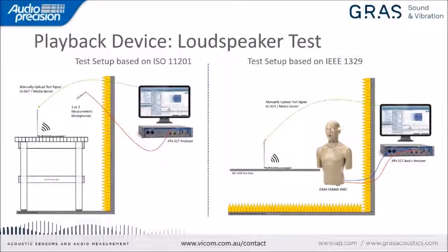Then the test table is placed inside a hemi-anechoic chamber where we typically have one free field measurement microphone at a position that should be described by the tester. Some laptop designers prefer to use two measurement microphones instead of only one. And when they use two, they separate them at a specified distance from the center to measure both the left and the right loudspeakers.